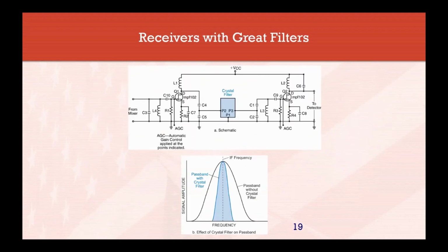Okay. This little circuit is trying to show the effect of the crystal filter that's right in the middle of that schematic. A couple of things to discuss about this. Just by general observation, and for no reason other than it's interesting to me, you'll notice those two FET transistors that they're using are Motorola MPF102s. That's a very old, very standard field effect, low signal amplifying transistor, FET device. But at any rate, they're using that as the amplifier on either side of the crystal filter.